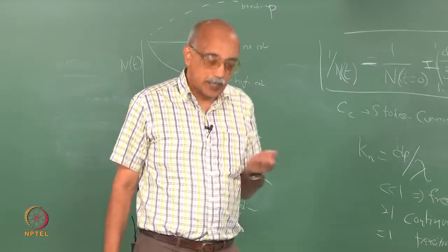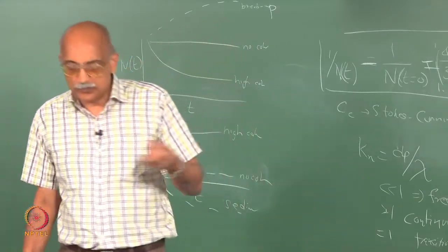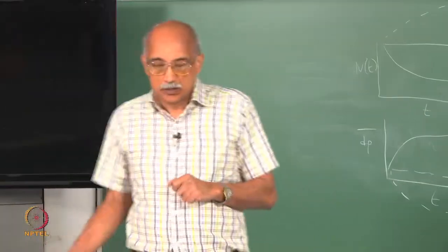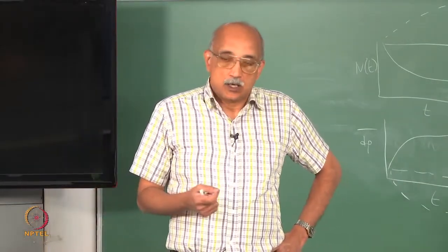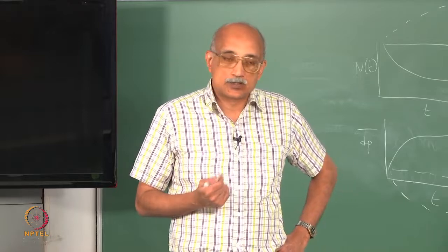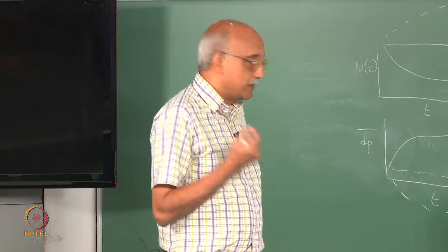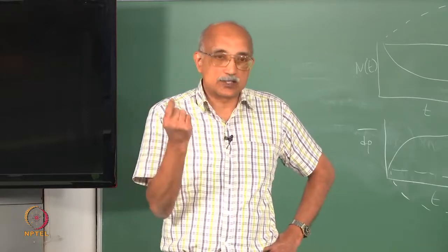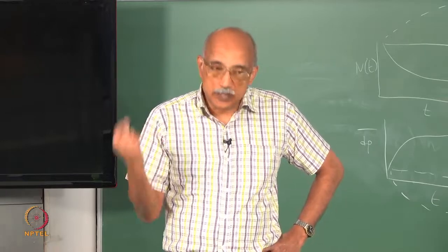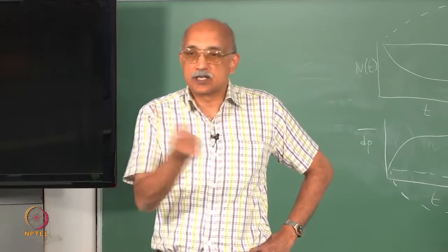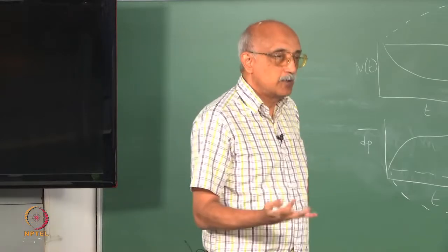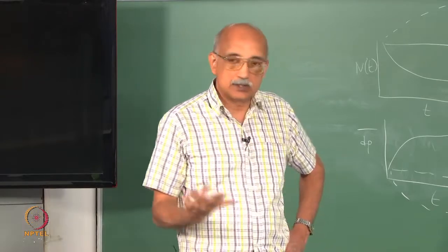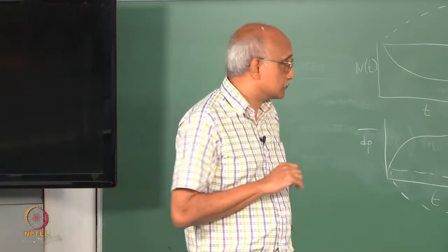And again, the reason for that we will see more when we talk about particle transport phenomena, but as particle size decreases, the diffusivity increases very rapidly, and so a very fine particle will diffuse much faster than a larger particle, which again makes it more likely that it will find its nearest neighbor and stick to it. So, anything that promotes the mobility of particles promotes cohesion. Okay? That is one simple way to look at it.